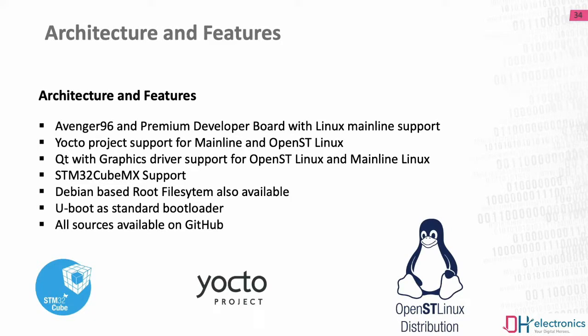On the next slide, I'd like to explain in a fast way the main features of our software support for the system-on-modules. First, as I told you, we support for both STM32MP1-based modules a mainline-based Linux version. This helps us in the further development and above all in the later maintenance of the BSPs for all projects. Then for all BSPs, Yocto project is supported. The next point is Qt support with GPU support for both board support packages.